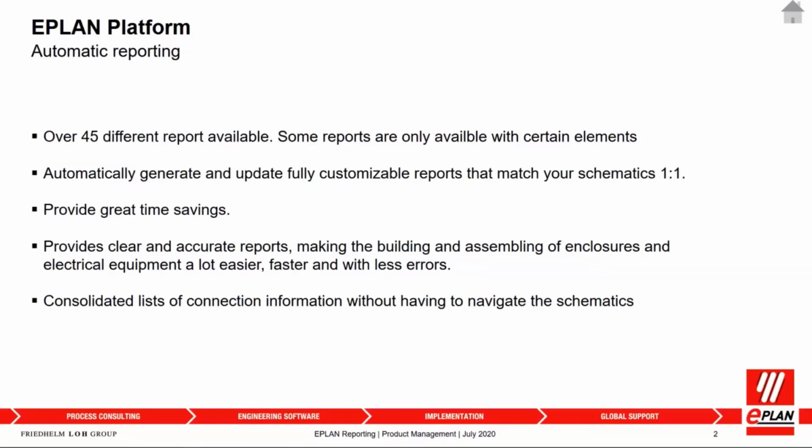So if you have a problem with your report, you can go back to the schematics, fix the schematics, and re-export or regenerate the report, which means that you can improve the quality of your schematics and minimize the mistakes in the schematics as well. You can also consolidate lists of connection information without having to navigate the schematics, meaning that the reports can be consumed by themselves without needing to have the schematics at hand to perform certain tasks.